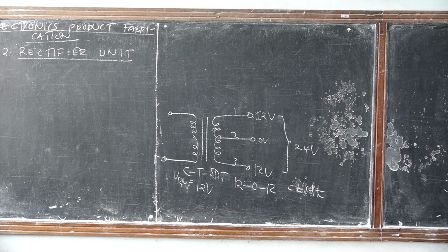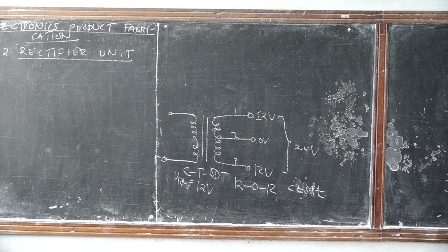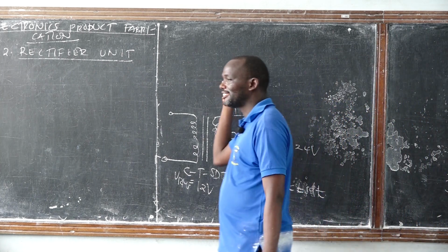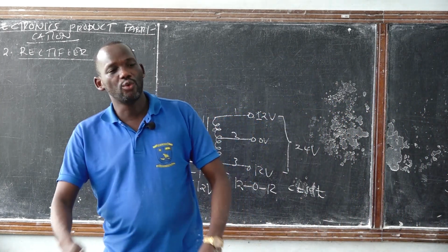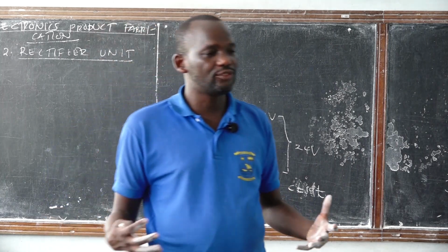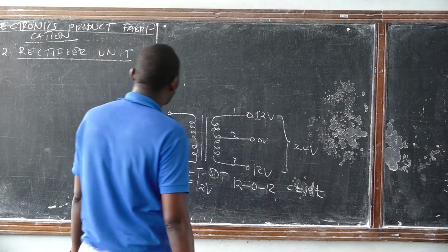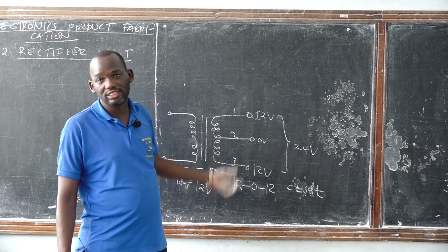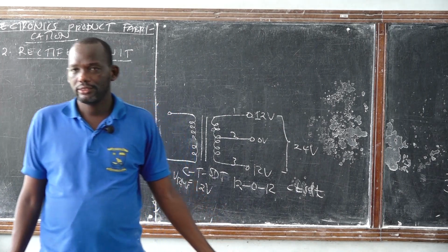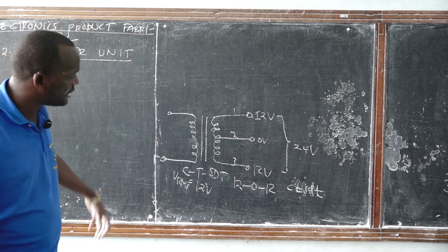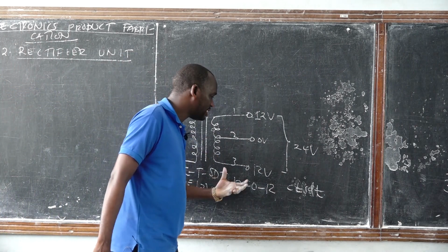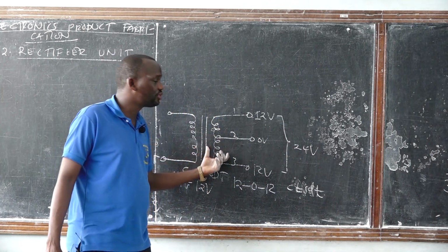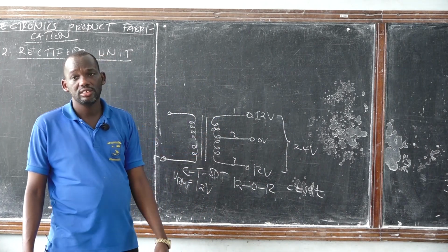Okay, Eliakim has asked the question: when are you going to use the center-tapped step-down transformer and the non-center-tapped step-down transformer? You are the one who has to decide. For instance, if in your design you need 12 volts, you may use either a non-center-tapped or a center-tapped step-down transformer. But maybe you need to use it in another system that needs 24 volts. In that case, you have to use the center-tapped step-down transformer.